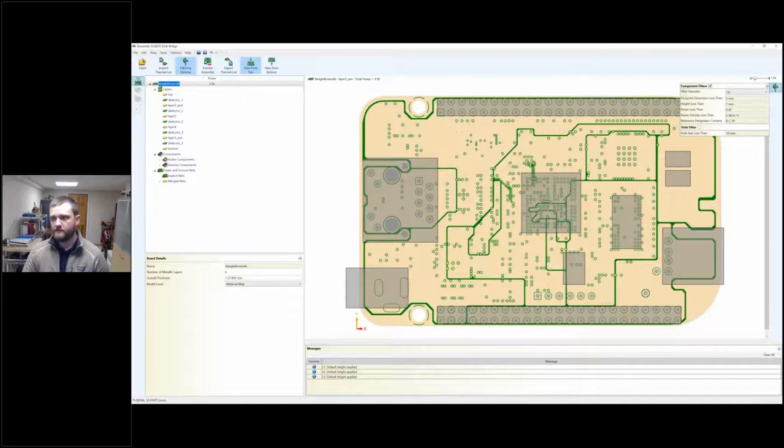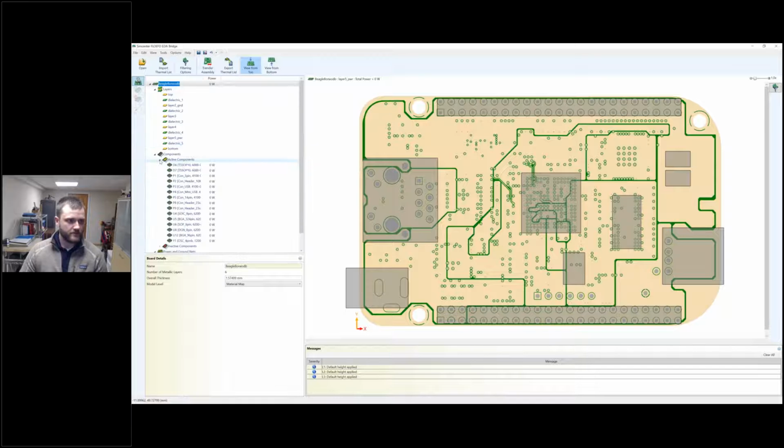But we have the ability here to filter based on dimensions of width and height, power density, and even hole size for really reducing the computational burden and the detail of these PCBs if we don't need them. But like I said, we'll keep that filter on at the default settings that we have here today, and you can see what we're including in the model. These are our active components, but notice there's no power assigned to these yet. We need to import our power data for those, and we have our inactive components here.